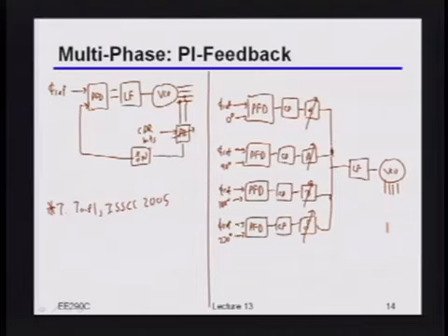No, what I'm saying is you have like 4 feedbacks to the PFD. So have them at different counters. Can you do something? Yeah, but I think that's basically 4 separate dividers. And remember, most of the time your phase errors are not going to be larger than a clock cycle. In fact, they're probably going to be smaller than 90 degrees, right? In fact, they should hopefully be much smaller than 90 degrees, because if they're bigger than that, you're probably making errors, right? So what's nice about this is that notice this node right here is low bandwidth, right?